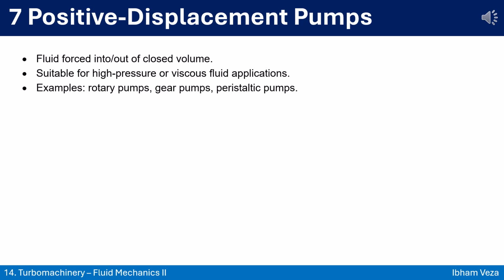Common examples include rotary pumps, which use rotating elements to move fluid through chambers, gear pumps, which use meshing gears to pump fluid by displacement, and peristaltic pumps, which use a squeezing action along flexible tubing. These pumps are the go-to solution when precision, consistency, or handling thick, sticky fluids is a priority.